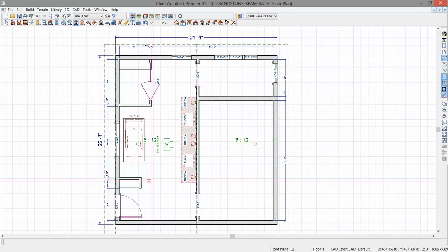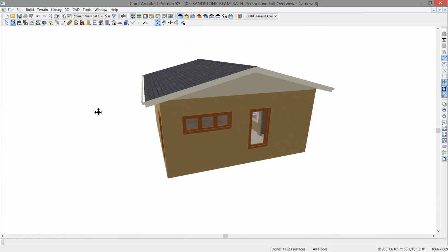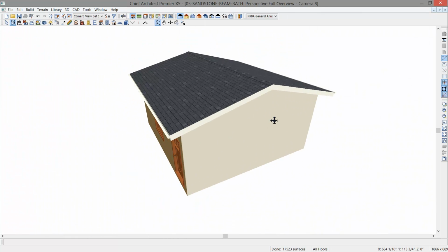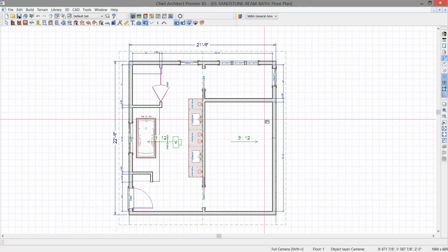And you can see our roof outline in our 2D plan view, and let's just take a quick peek at the 3D overview here. So you can see our roof so far. Again, I'm not really after the exterior. Let's close that down. And once we've generated the roof, that creates an envelope that, when I stick in any members like a timber beam, it's going to snap to that envelope. So it makes it pretty easy to do that design work.